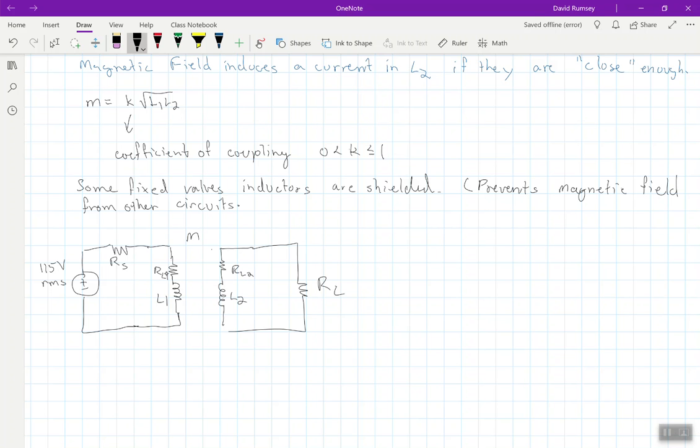Okay, so an inductor is actually going to have some kind of resistance because it's a wire. It's wire wound and everything. So this is a model for that inductor. We've got some resistance for inductor 1 and then the actual inductance, resistance for inductor 2 and then its actual inductance. And then I've got my source resistance, my load, and I'll still have my dot convention here.